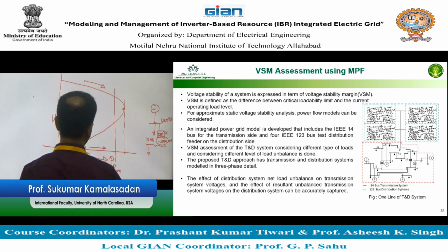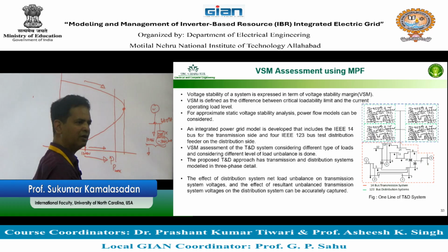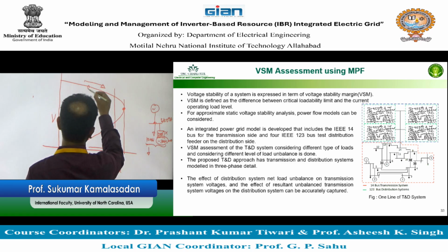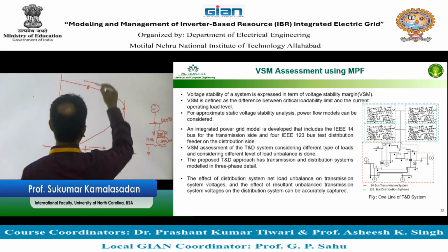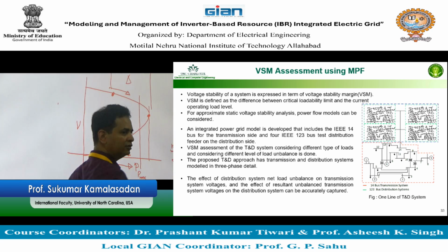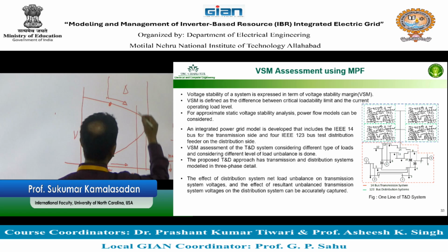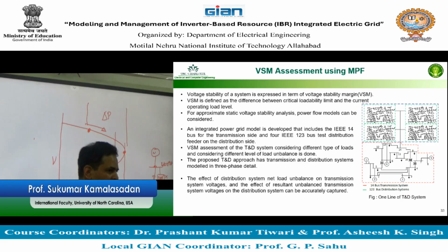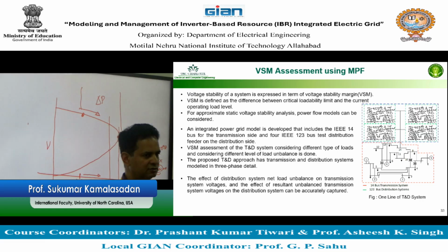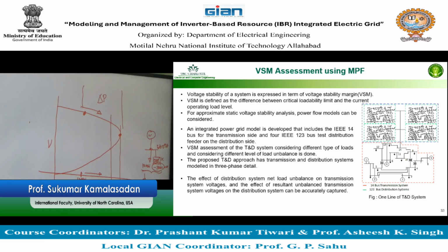So you may ask, okay, is that the only thing you can do from the PV curve for stability? No. You can also say that, well, I am here. What will be my margin for stability? So how much P can I push on this bus before the voltage on that bus collapses? Is that useful?